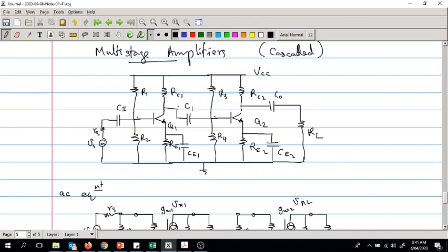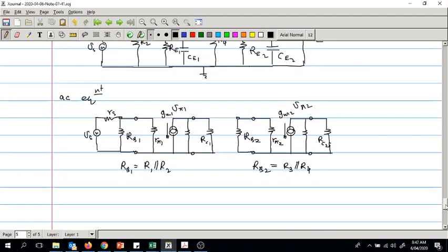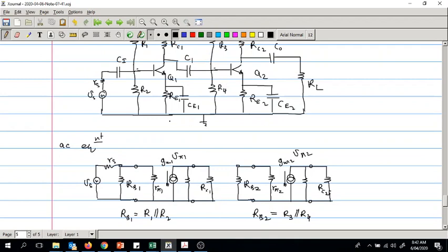Now as you can see here, what is the replacement for that C1? You can remember, we did it in the second year electronic fundamentals module, which is a short circuit. Yes, a short circuit. So this is fully connected. The collector of this, that is this point, is connected with the base of this. What else do we have?